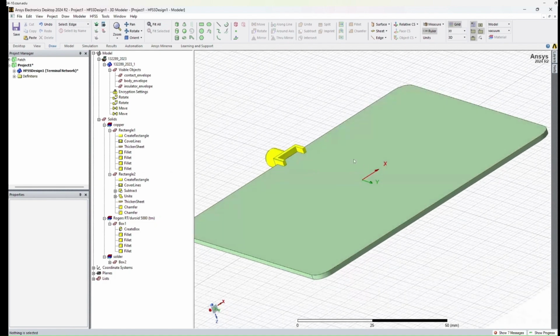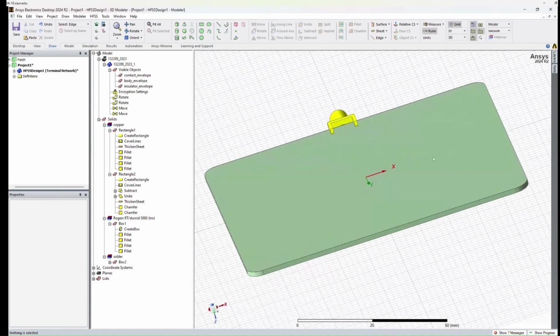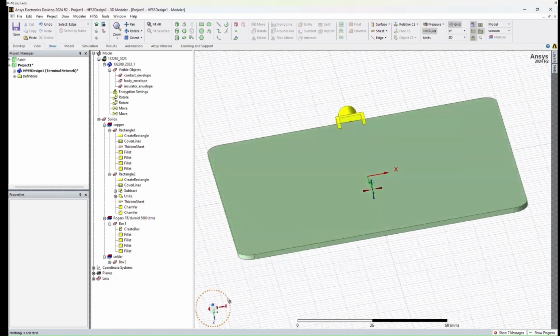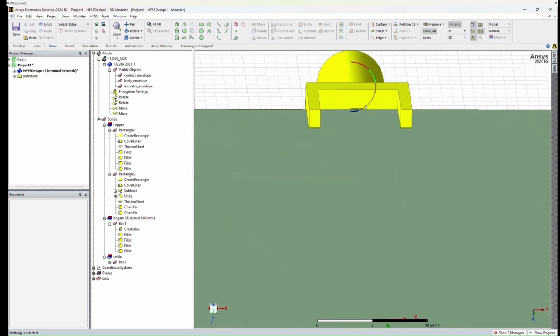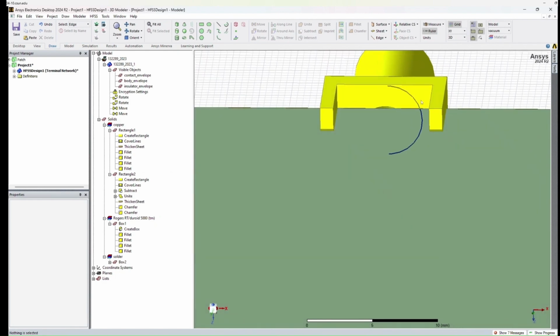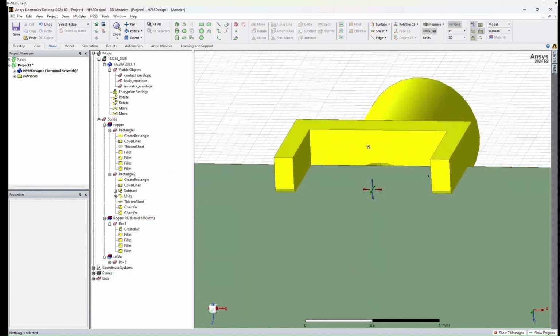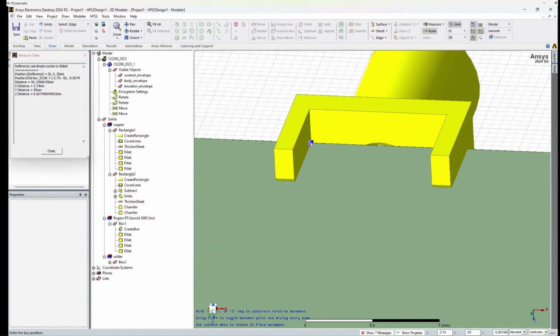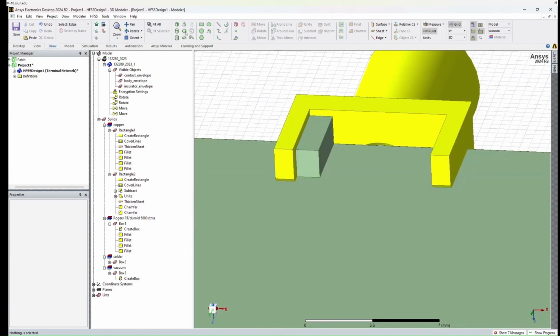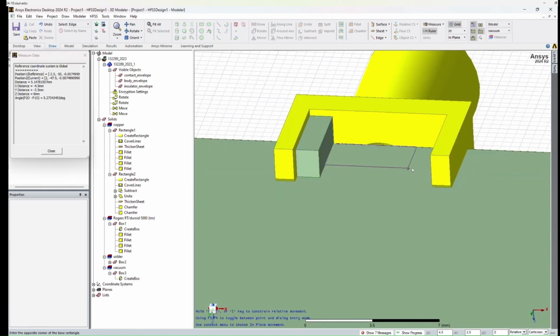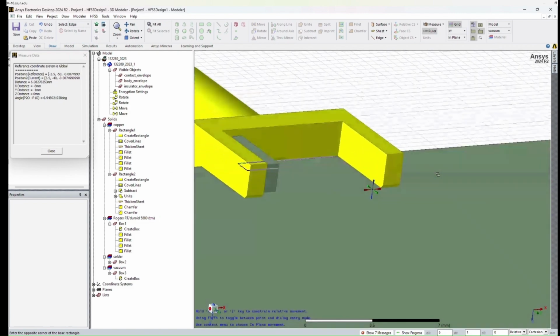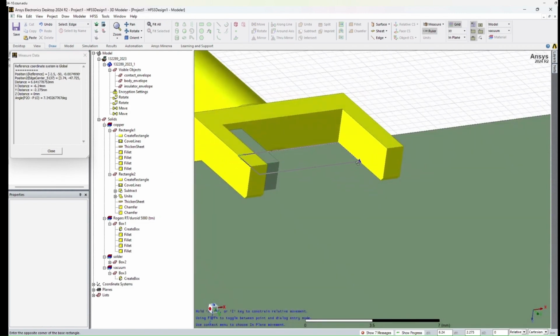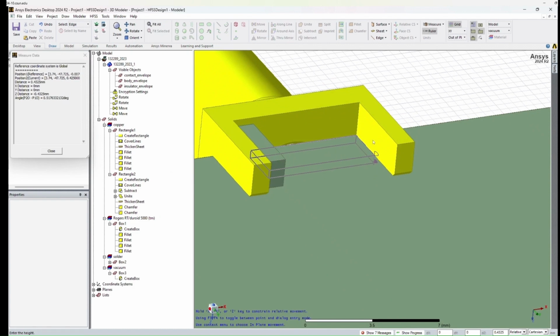So then for the bottom, we're going to do something relatively simple, and we don't have to do any subtraction because there's no intersecting components. So what we're going to do here is just draw 3 boxes and unite them and then shave off the edges once again. So I'm going to snap to the corner here, draw a box that goes up most of the distance, and then just repeat and keep drawing boxes until they fill this whole area basically, and use the edge of the connector as reference points.